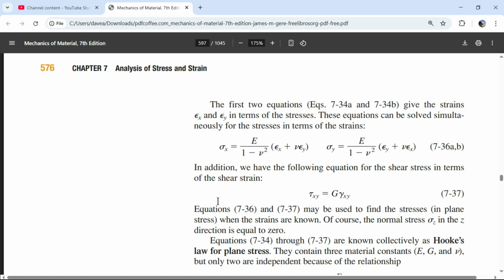And I don't think this book covers that. Maybe it does, because if you have something in hydrostatic pressure, it's not like you're at a neutral. If you have a material under the ocean that's in hydrostatic pressure and you're pulling on it, you wonder how much you can pull on it. Or pushing on it, that would be a better thing. If I have a bar up on the surface of the earth and I push on it on both sides, or even just a chunk of wood, I can only put so much compressive stress before it fractures at 45 degrees due to shear.